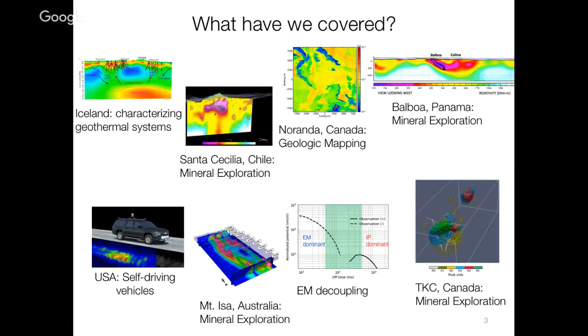GPR, we went through the basics of GPR, showed you some of the wave fronts and how things decay. We looked at the application for self-driving cars, which was just kind of interesting. And for GPR, a lot of applications for geotechnical engineering and near-surface work. If you're trying to find small voids in roads or things like that, tow a GPR system over, and that'll help you out. And we went to induced polarization.